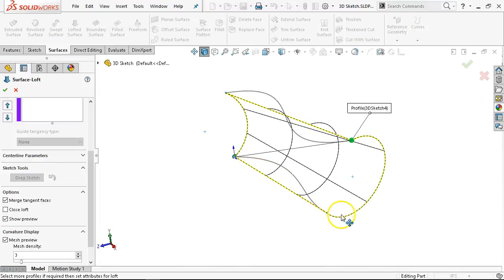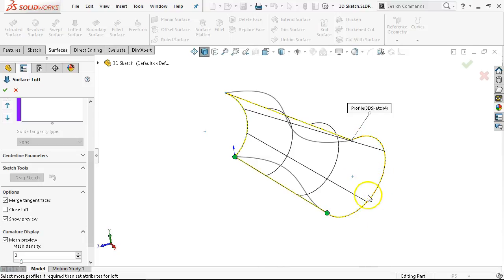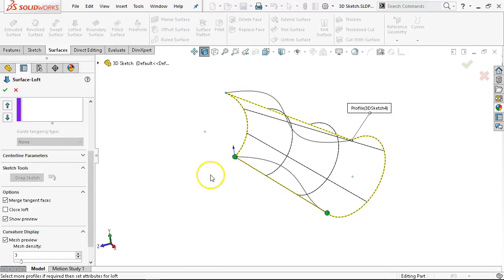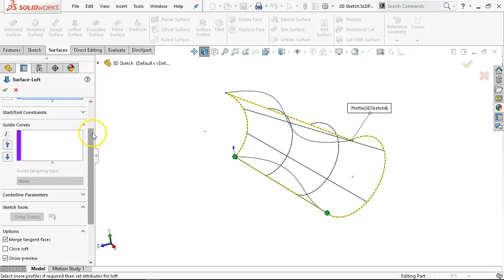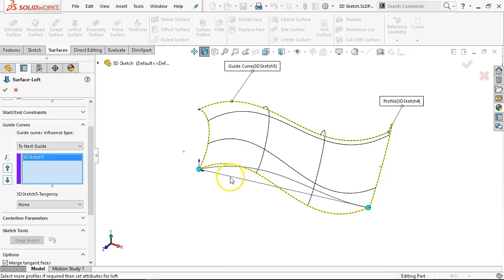What ends up happening is we drag that handle along. It's trying to connect just to the endpoints. If we could drag that handle along the curves, then it goes to twist, and once you have a self-intersecting shape, it's going to fail. It's not going to show you the preview. All right, so we go to the guide curve. It gets a little wavier. Guide curve number 2.